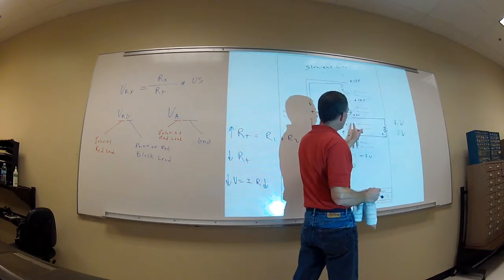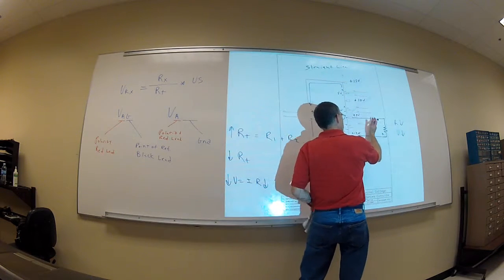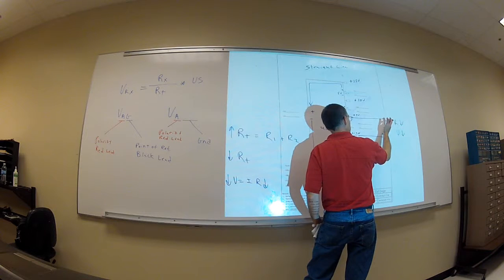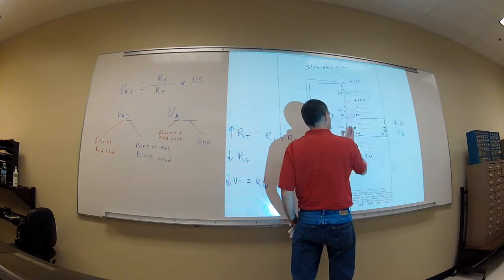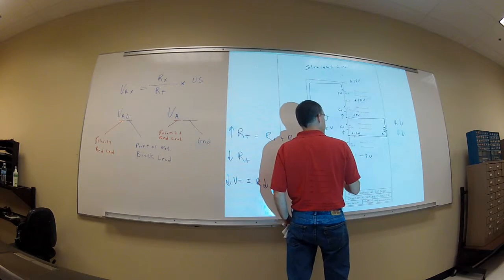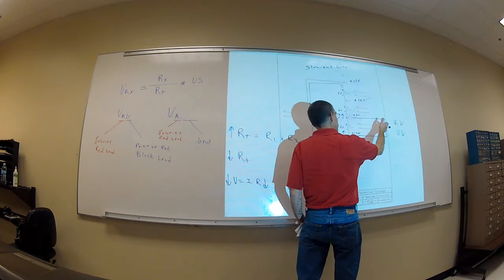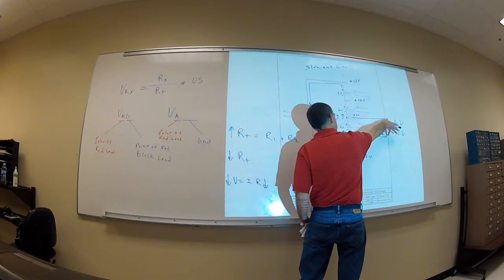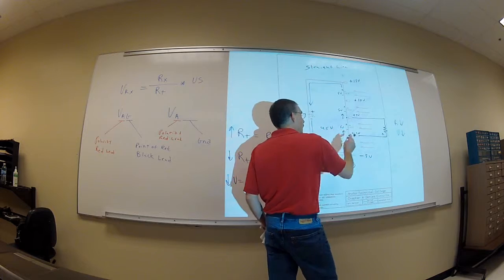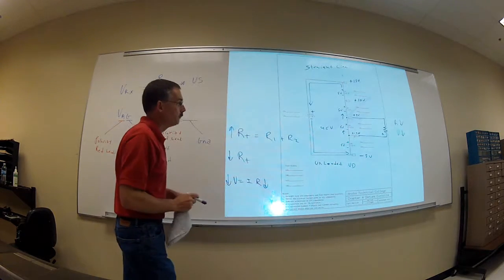And so that's all they're really looking for you to do, just put that resistor across the other resistor in our voltage divider, the unloaded voltage divider, and we're just going to measure that voltage across there, and we're going to watch that voltage start to drop as we put in